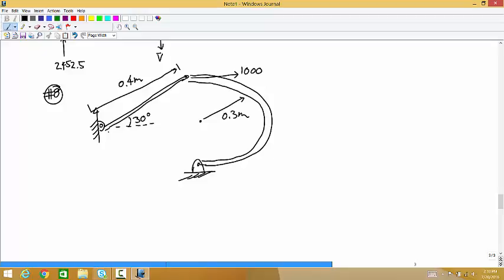It's a funny-looking truss, but it's still a truss. If you wanted to calculate the internal loads in this curved member, things would get a little weird. But it's still a two-force member, is what I mean. And so you can still use whatever method you use to find the external loads in trusses. Yes, it's a curved beam. Did I say straight? It's a curved beam. There are curved beams.